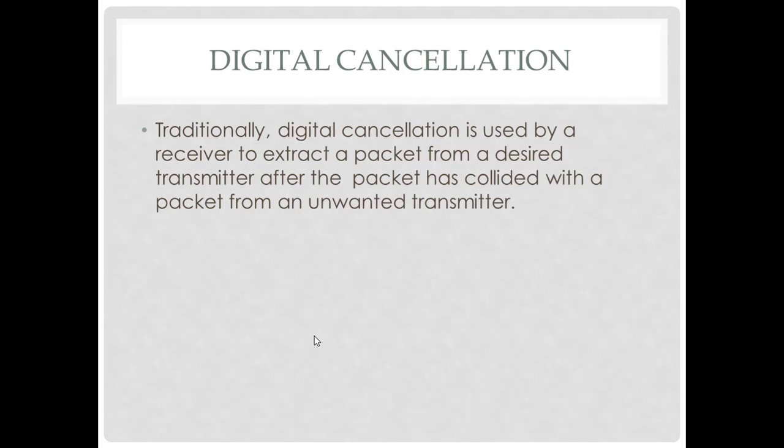In case of canceling self-interference for full duplex, the transmitted symbols are already known, and thus decoding is not necessary in order to reconstruct a clean signal. So the main challenge in subtracting the known signal is in estimating the delay and phase shift between the transmitted and the received signal.